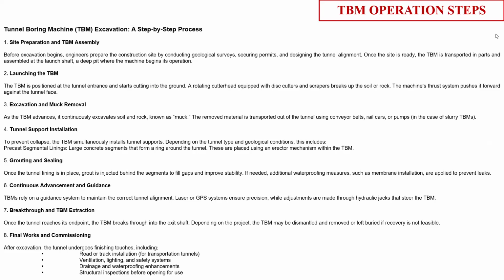after the TBM machine has gone through the breakthrough, we check every individual segment, and we find that some of the segments get cracked at different positions. It can get a crack at 3 o'clock, at 6 o'clock, at 9 o'clock. It can get a crack at the crown, at the center line, at the spring line. So we first check the nature of the crack and what type of crack it is. Is it a dry crack or a wet crack, whether there is water ingress, and the main thing, what is the width of the crack. Sometimes we also put a crack meter on the segment and monitor whether the cracks are opening further, or whether they are self-healing cracks. Sometimes the crack gets healed automatically with time.